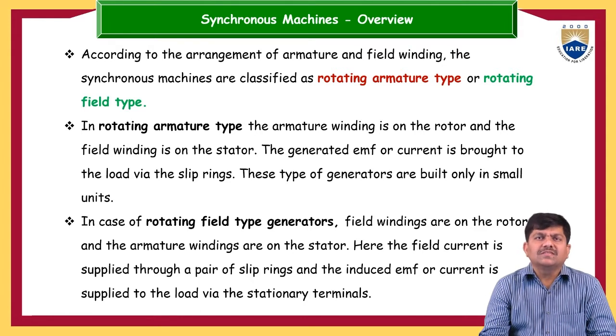Alternators are nothing but synchronous machines. First, why is an alternator called a synchronous machine? Because, unlike an induction motor, it always rotates at synchronous speed. Synchronous speed is 120 times the frequency divided by the number of poles. But in the three-phase induction motor, the rotor is always behind the synchronous speed. It always tries to reach the synchronous speed, but never succeeds. That is the magic that happens in the induction motor.